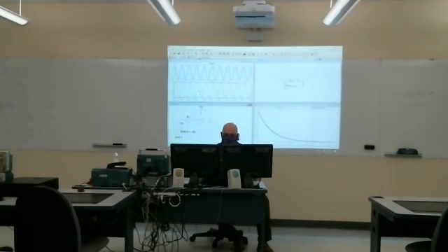Let me try one other type of input. If you integrate a square wave, you should get a sawtooth type waveform. So if I make this a pulse on for 1 micro, I'll get rid of those things, 1 micro, and then have it on for 1 second with a period of 2 seconds.